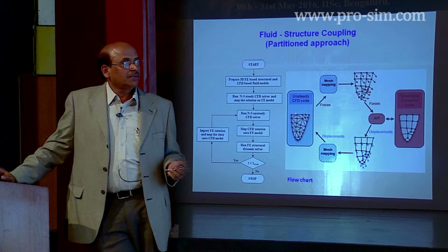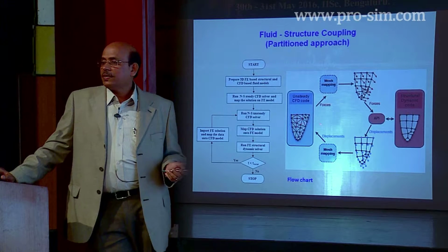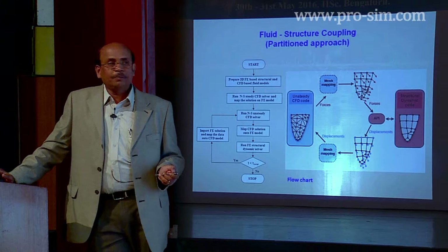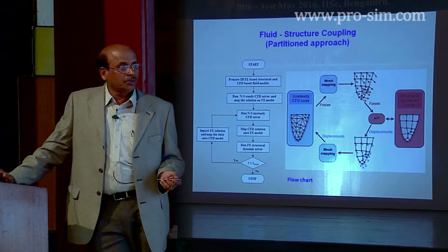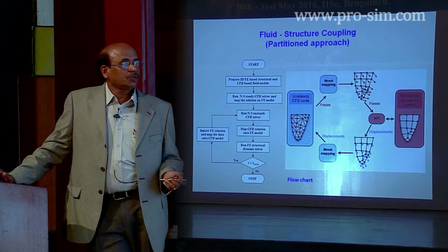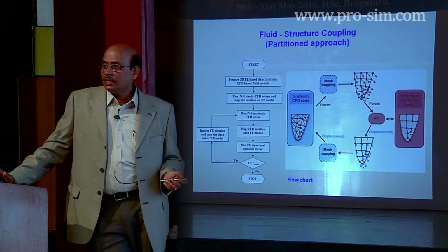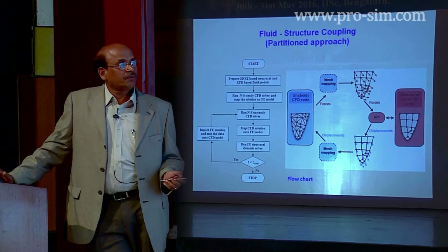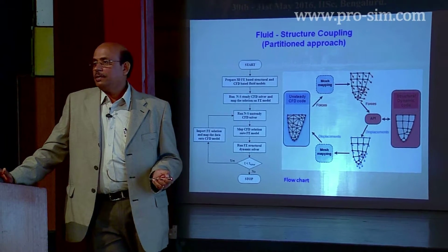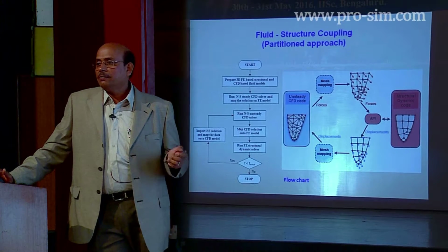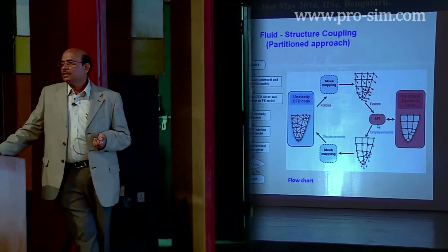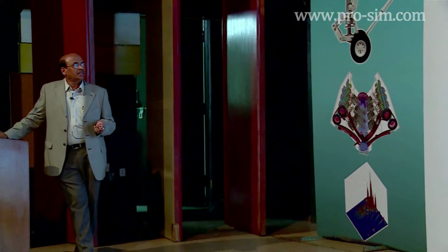On one side we have the CFD code with the complex finite difference grid. On the other side we have the finite element code. Earlier we didn't have the finite element code; here we do. The finite element method calculates the displacements, which go as input to the finite difference method for solving the aerodynamics. The aerodynamic equations are solved, from which pressures are obtained, which are converted into forces, which are given as input to the finite element method. Okay? This goes on iteratively online, and ultimately we get the complete displacement time history curves like what we showed earlier.